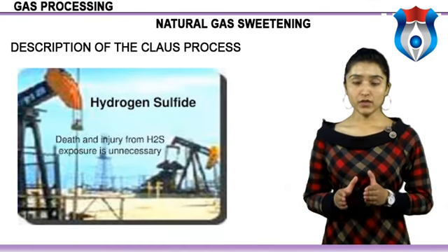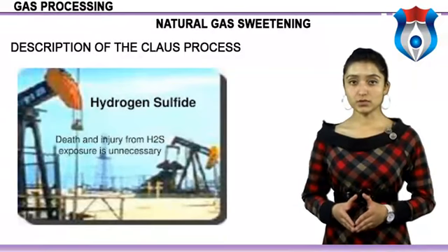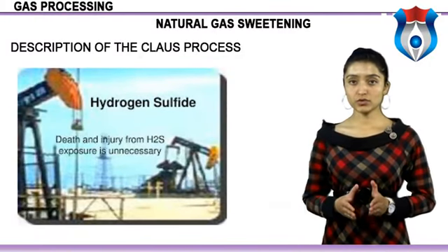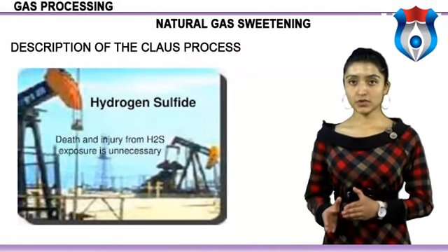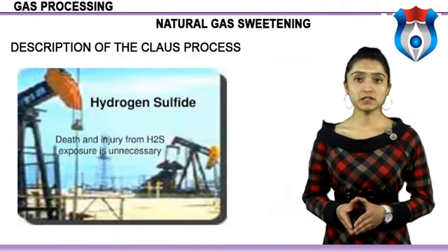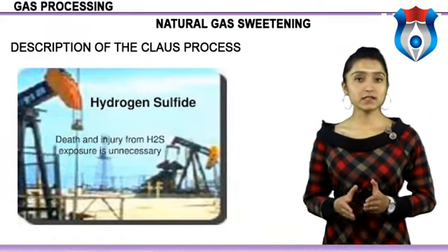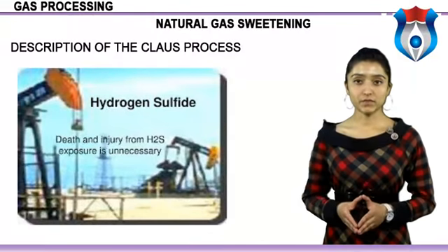Catalytic step: the remaining H2S is reacted with the SO2 at lower temperatures, 450 degrees Fahrenheit, about 200 to 350 degrees Celsius, above the dew point of sulfur to prevent condensation on the catalyst, to make more sulfur. A catalyst is needed in the second step to help the components react with reasonable speed.